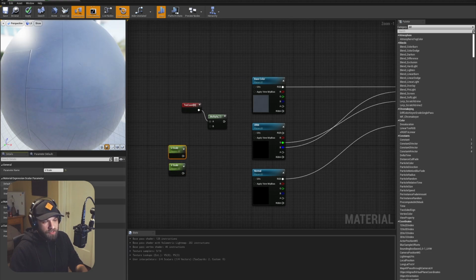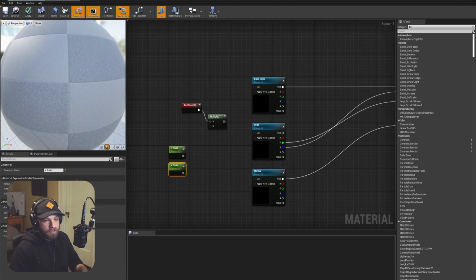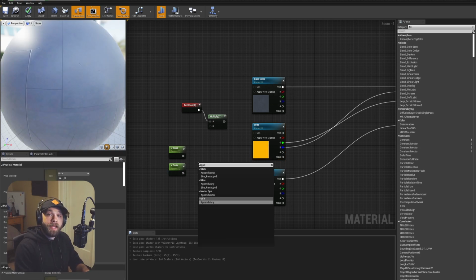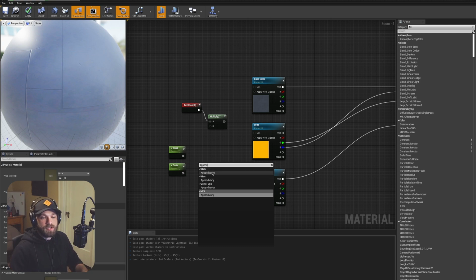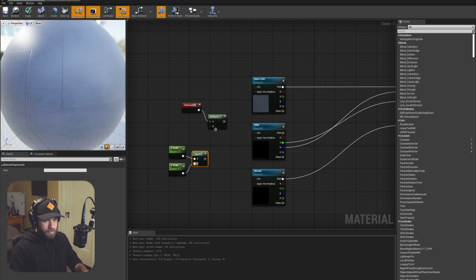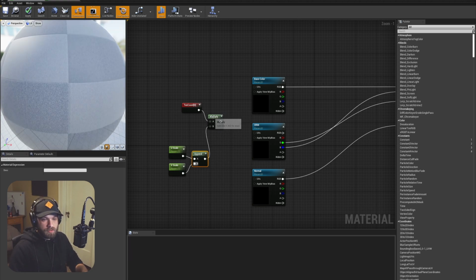So imagine if these are set to default of 1, the ratio of 1 to 1 would be typically what you see. That's what these textures are currently set to, right? So we're going to get an append node, which will take those 2 individual vectors and combine them into a vector 2 instead of 2 vector 1s. So now they reference a UV. They actually create a UV coordinate, and then we can plug that into the B of our multiply.